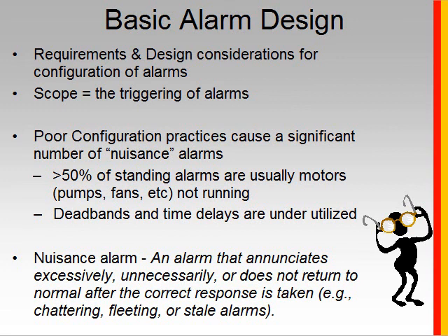It also addresses setting correct parameters such as alarm deadbands and on-off delays, which can be tuned to make sure that alarms only occur when there's truly a problem situation. Now, there's been several studies done by the ASM consortium that have shown that fine-tuning these alarm deadbands and on-off delay parameters has a significant effect on the alarm load on the operator.